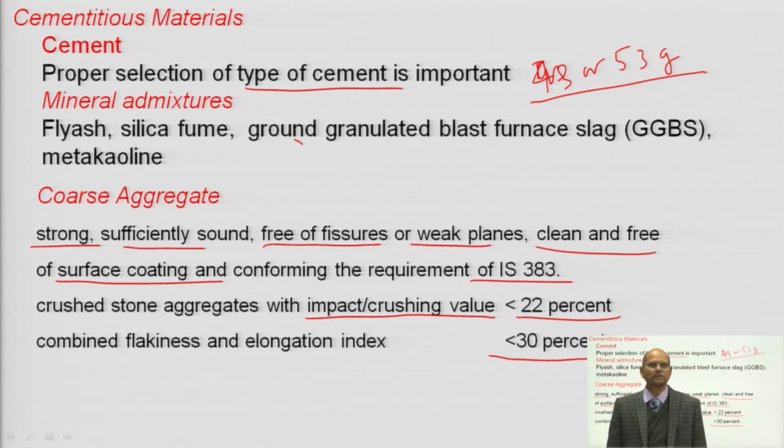So, selection of coarse aggregate is important, and as I had discussed, the size should not be bigger. Generally, for better strength you can use 15 mm and downsize, and not more than 20 mm in any case. So, once you want to produce even greater than 80 megapascal concrete, then we have to use 12.5 mm and downsize coarse aggregate.